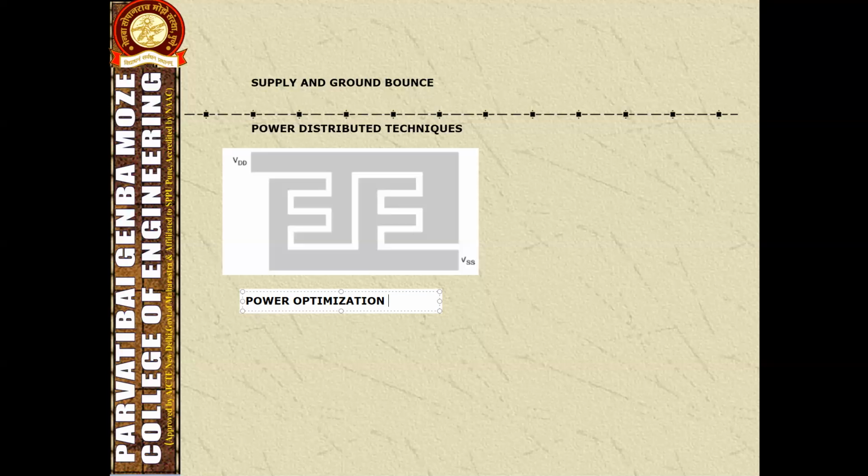One way to reduce the power consumption is to reduce the capacitance driven by the gate. However, since the gate consumes almost no power when quiescent, the most effective way to reduce its power consumption is to make it change its output as few times as possible. If there is no change in the output value, the gate does not consume power. Logic gate circuits are designed to reduce the number of unnecessary changes to the gate output.